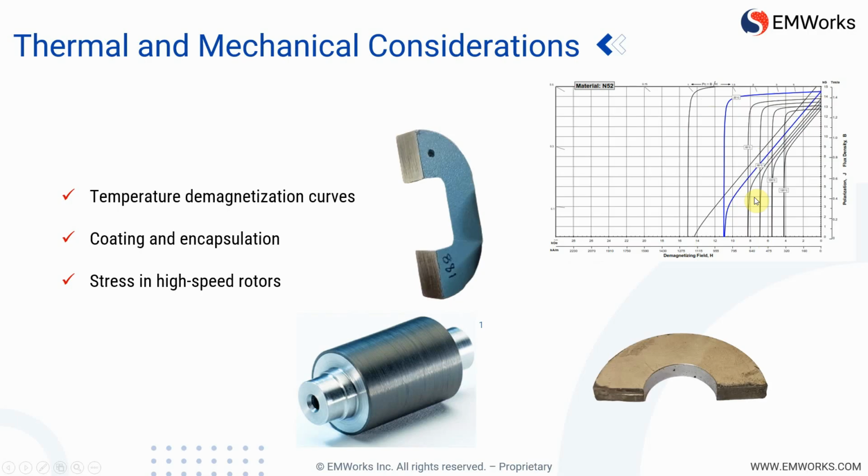Thermal management is equally critical. Magnets are typically the most temperature-sensitive components in a motor. Thus, cooling strategies must ensure the magnet temperature stays below its maximum operating point, often between 80 to 200 degrees Celsius for NdFeB and up to 350 degrees Celsius for SmCo.